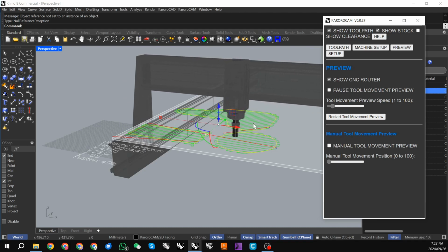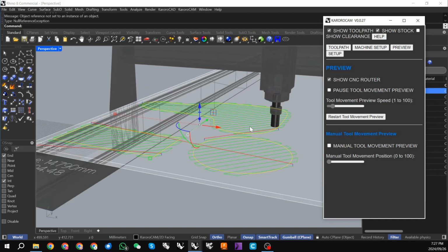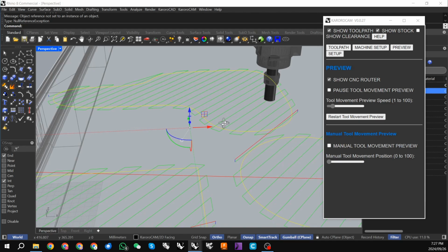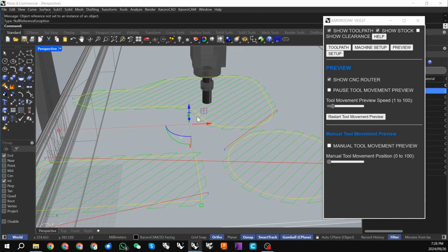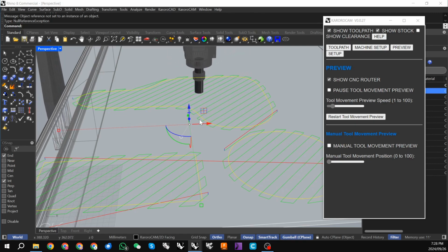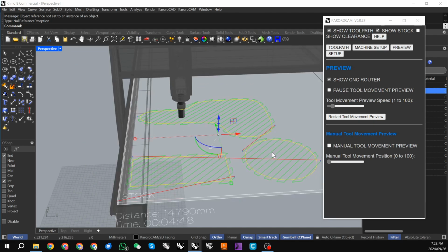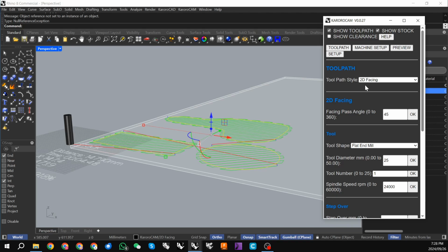I think that's looking absolutely fine. I'll just get it to start the last one. Especially with these stranger shapes, you will guarantee that you'll actually get the edges all of the way around if you have the tool come to outside of the stock curve. That's all looking excellent. So we'll stop that, go back to toolpath,